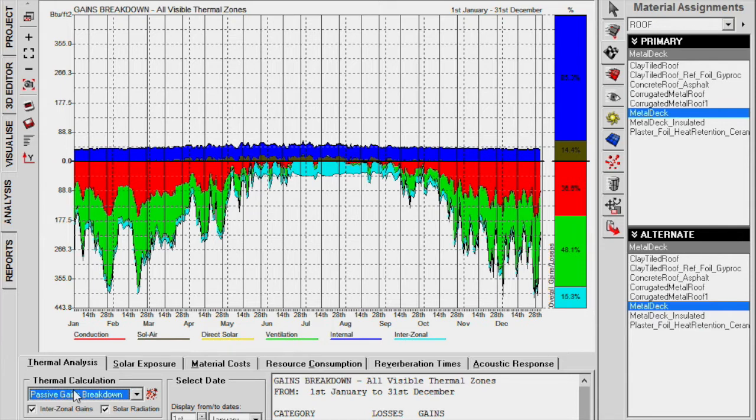There's something else, though, you need, which is something called the solar heat gain coefficient. And that's all about the amount of radiation that's flowing through. So we can decide whether we like the radiation flowing through, because it's heating things up, or not. You know, and that's actually a window property we can specify. Let's talk about the last chunk, which is this direct solar radiation, because that's actually kind of an interesting property. Let's think about where that applies the most.